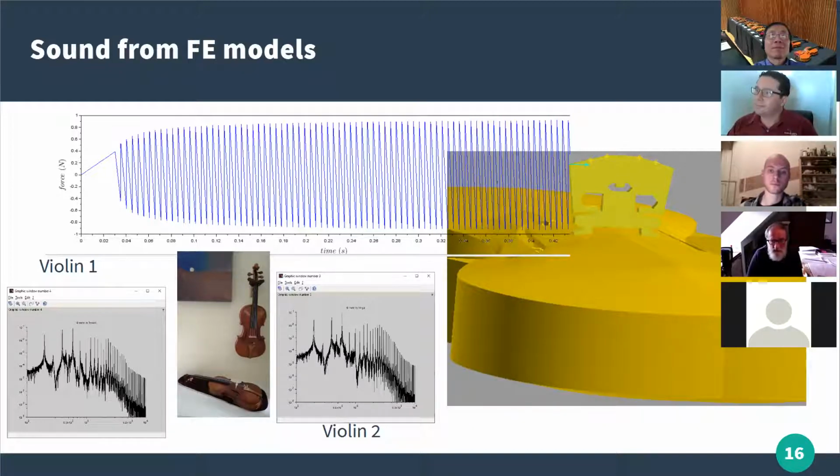What you would need to do to use that is simply one extra stage from your model. You need to generate the impulse response from your model at the bridge, and then do a convolution of that with a realistic signal. It's fairly straightforward. You probably do a sufficiently high resolution frequency response and then an inverse FFT, and you'll get the clonk sound of the violin. Then you could convolve it with a bit of real violin playing, and that might change your perspective on the comparison you've just played us.